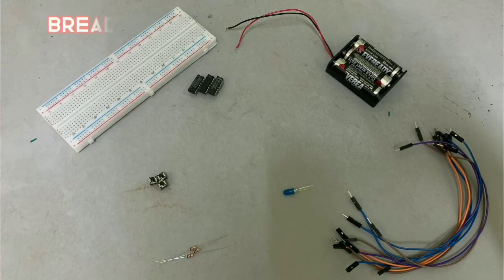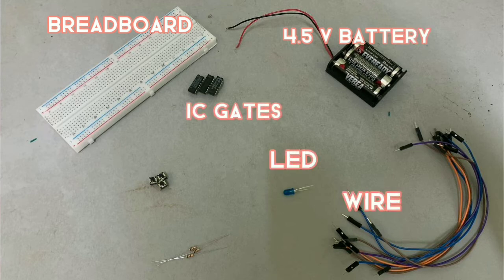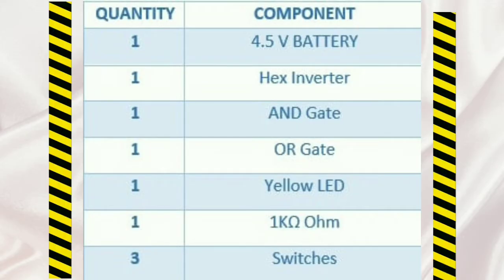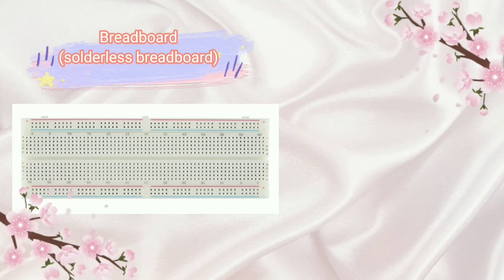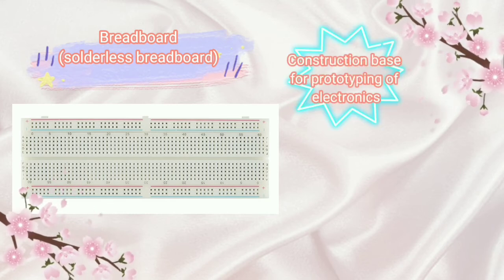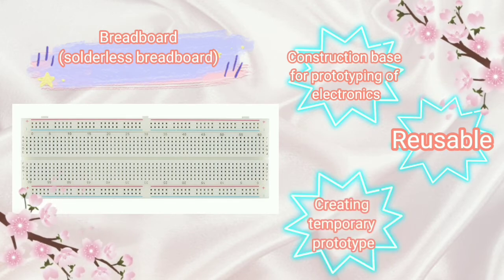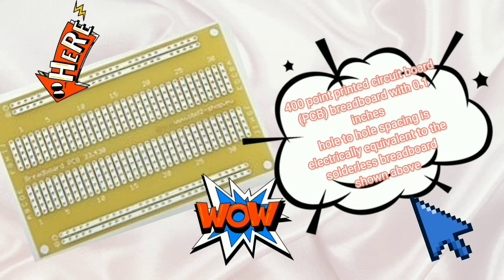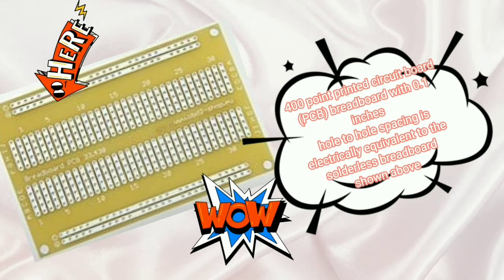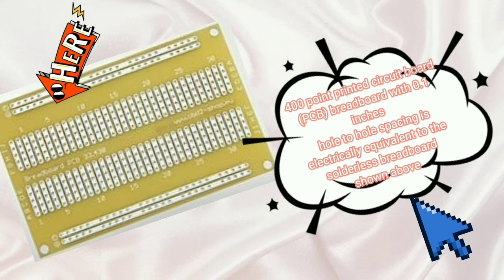The first component is breadboard. Next, 4.5 volt battery, IC gates, LED, wire, switches, and transistor. Let's move to the details about the component used. First is breadboard or solderless breadboard. The function of this component is a construction base for prototyping of electronics. It is reusable because it does not require soldering, so this makes it easy to use for creating temporary prototypes. 400-point printed circuit board PCB breadboard with 0.1 inches hole-to-hole spacing is electrically equivalent to the solderless breadboard shown above.